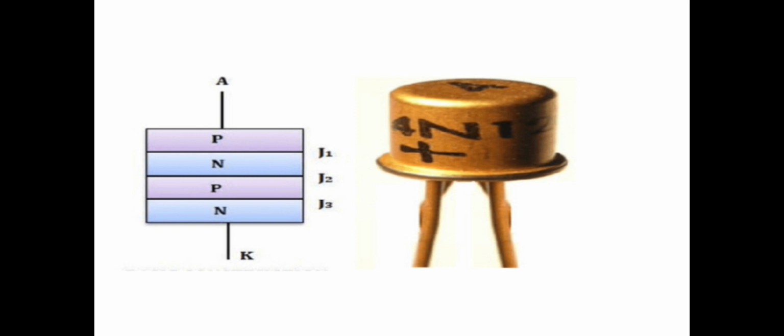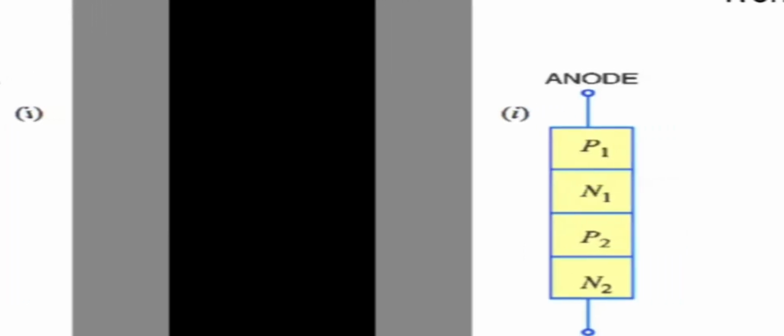Shockley diode is not widely available commercially. Still, it forms the backbone of devices like the diode SCR. It operates in two states, either on or off. Thus, it is used as a switching device. It is also called PNPN diode because of its construction architecture. It is a two-terminal device, that's why it is categorized as a diode.